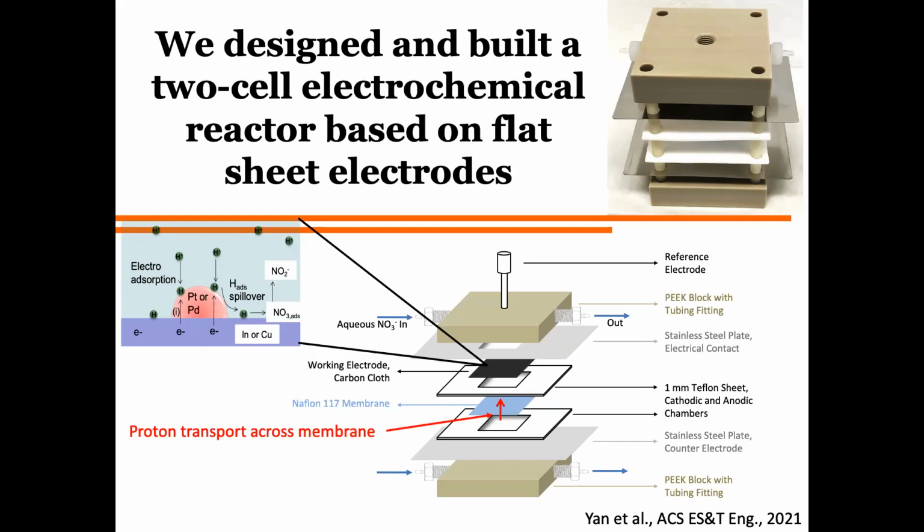But oftentimes these fuel cell designs, the mass transfer is limited by the Nafion membrane, proton transfer rate, sometimes the electrode flooding, when you can't get rid of the byproducts fast enough. What's your projection on probably similar problems I can anticipate that would arise from such reactor design, and how you would potentially overcome these mass transfer limitations to scale this up?